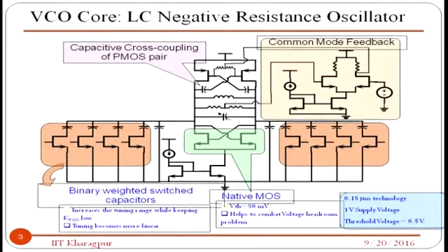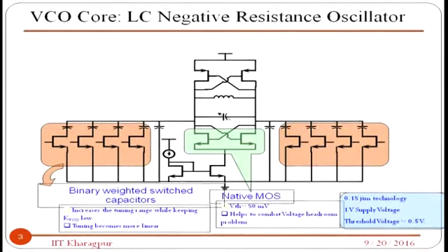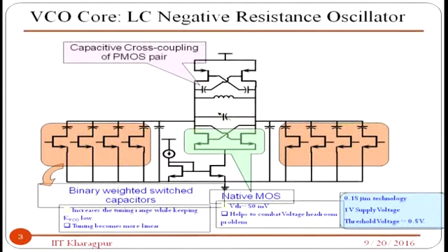This is how a negative feedback, a common mode feedback with a negative approach, can be balanced, and you can have equal voltage combinations in both cases. That is how you should be able to bias this cross coupled pair using this technique. So, you can use one cross coupled pair with those capacitors, and also use this common mode feedback to ensure stable and symmetric operation of this VCO.